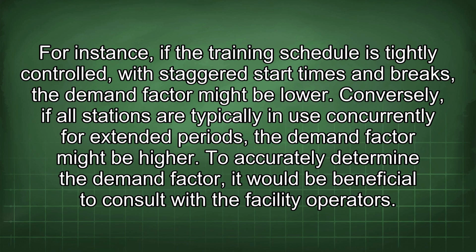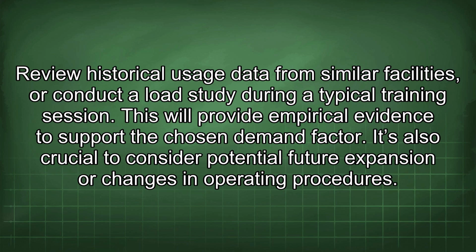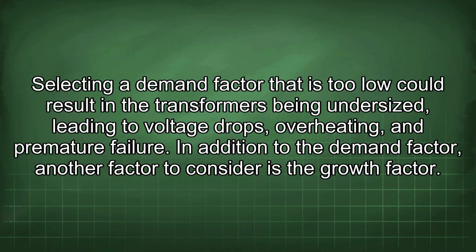To accurately determine the demand factor, it would be beneficial to consult with the facility operators. Review historical usage data from similar facilities, or conduct a load study during a typical training session. This will provide empirical evidence to support the chosen demand factor. It's also crucial to consider potential future expansion or changes in operating procedures. Selecting a demand factor that is too low could result in the transformers being undersized, leading to voltage drops, overheating,